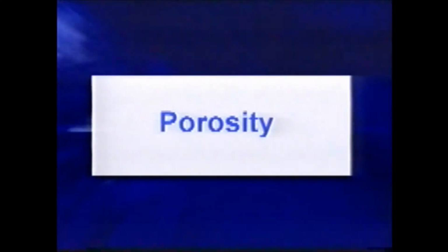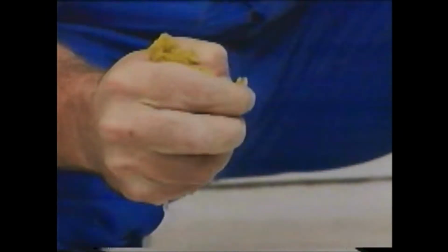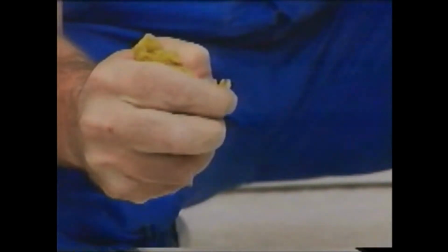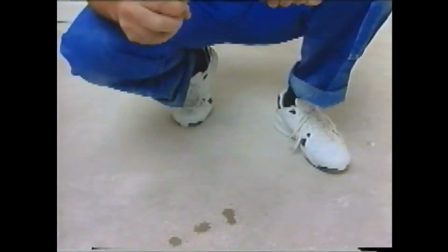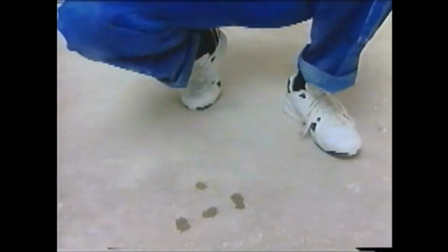The subfloor shall also have a normal absorbency to allow bonding of the finished material. Porosity may be evaluated by sprinkling a few drops of water on the subfloor. If the drops are absorbed within 1 minute, it is porous and absorbent. If it takes between 1 to 10 minutes, the absorbency is normal. If it takes more than 10 minutes, the subfloor is not absorbent. For each category of porosity, there is a specific type of primer.